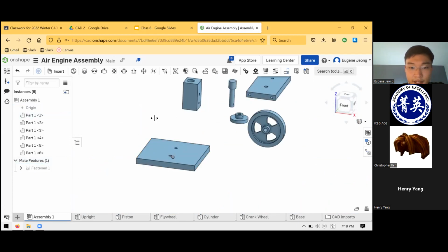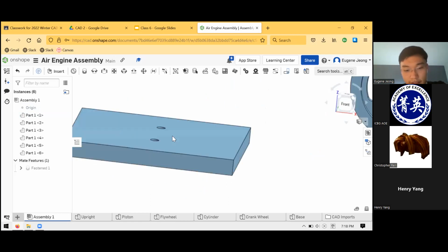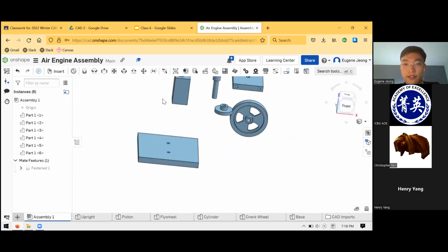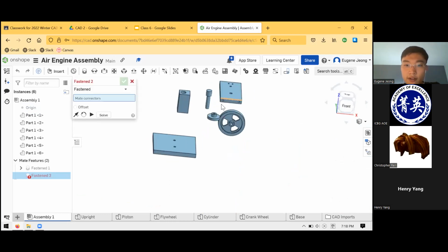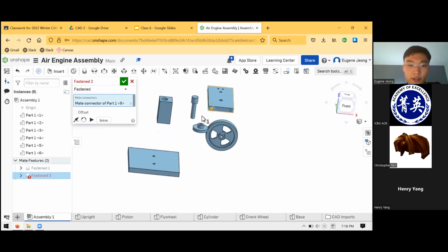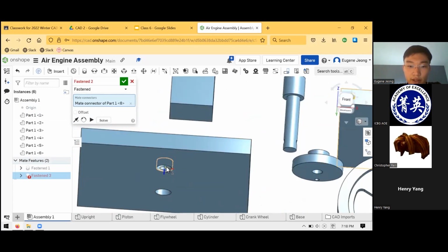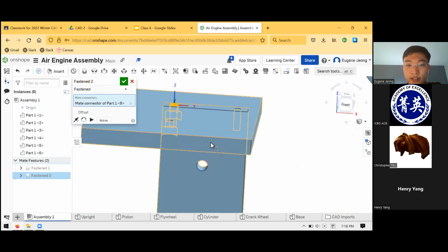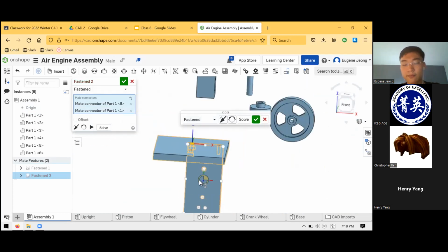And the reason for that, you can imagine, like I said, the counter bore is there so the head of the bolt can sit on the part and be flush with the bottom surface. So the bolt's going in this way through the bottom where the counter bore is, and then it's threading into here. So the reason this hole is threaded is so that the screw can come in through here, and then the part that sticks out is threaded, and it would thread into the upright.